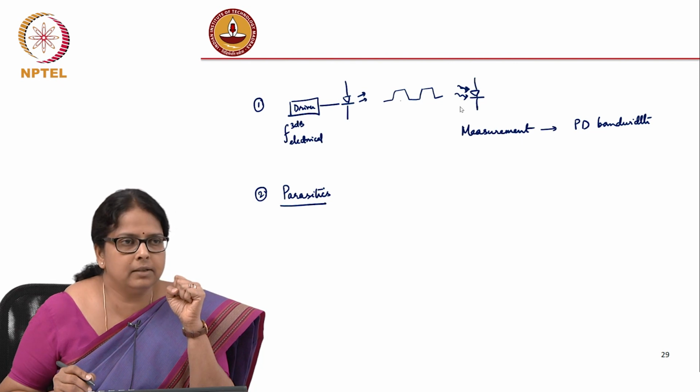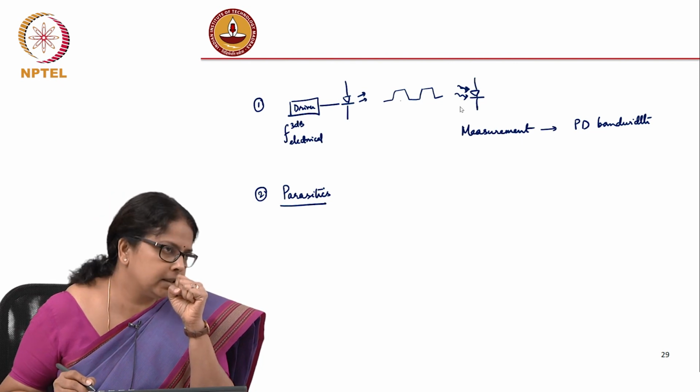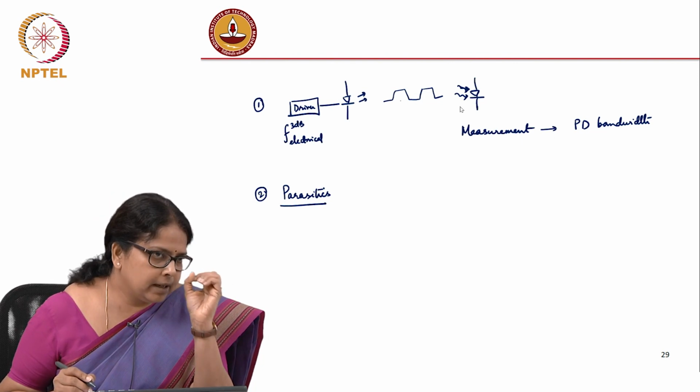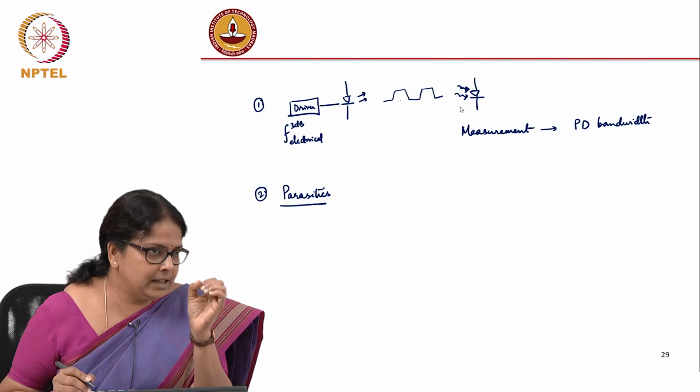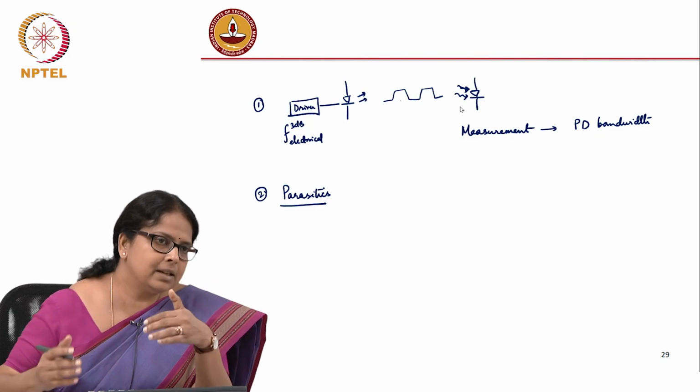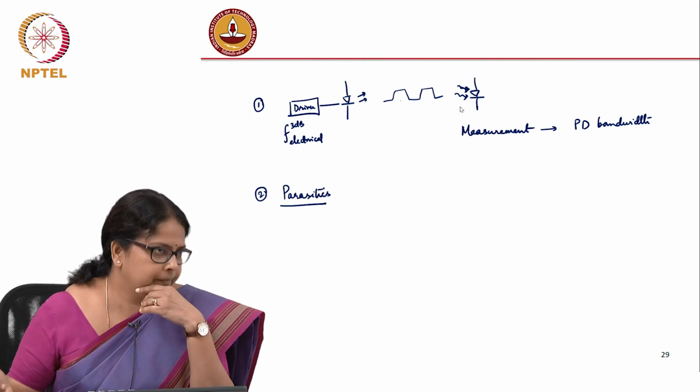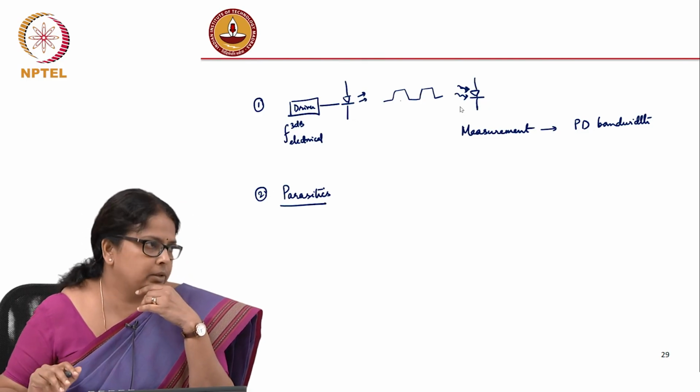factor that you need to consider when you are measuring the LED bandwidth is parasitics. Let us say you are using a cable which has a large capacitance, and it is like a transmission line which now limits the bandwidth of operation of the LED. That is something you need to consider.